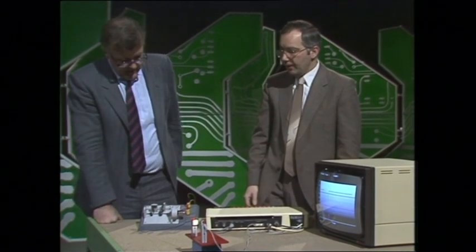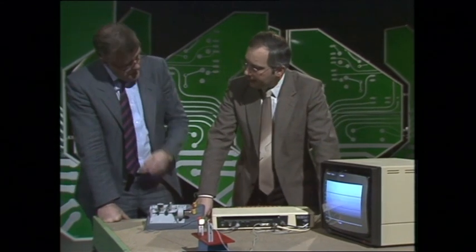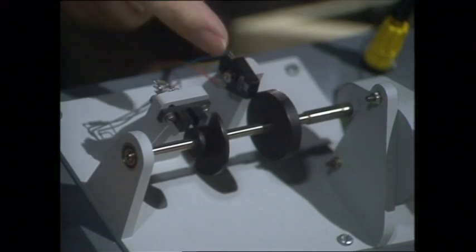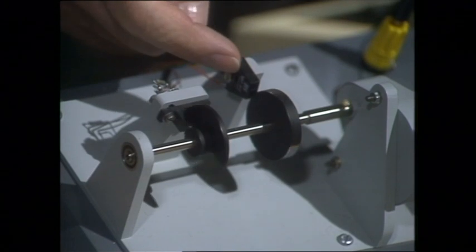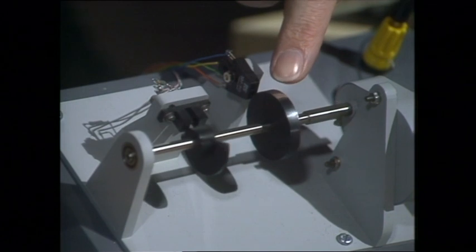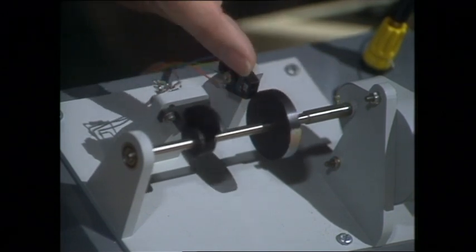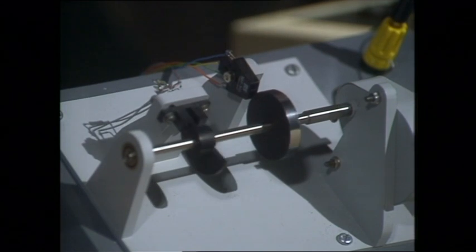Very easily. Now, yet another use of optical sensors is for telling whether a shaft is rotating and how fast it's rotating. This sensor here, used on the buggy, emits infrared light, which is reflected off this silvered strip on the disc, and it's detected below. And so the computer can know from the obstructions how fast the shaft's rotating.